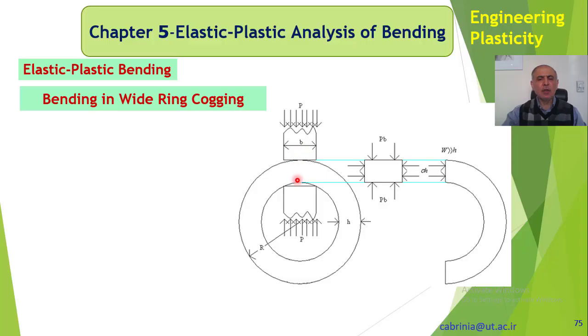This ring also rotates. We rotate the ring and press it so that the diameter expands and you get a bigger ring with a thinner section. The cross-sectional area is big at the beginning, and as we continue pressing and rotating the ring, the cross-section becomes smaller.